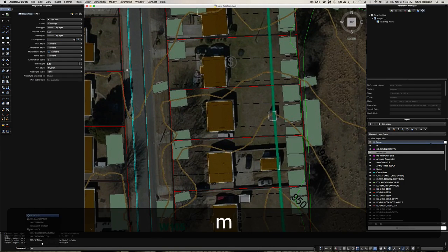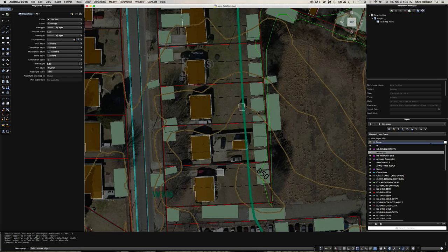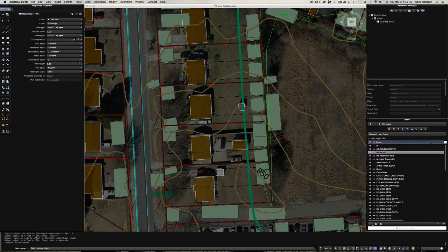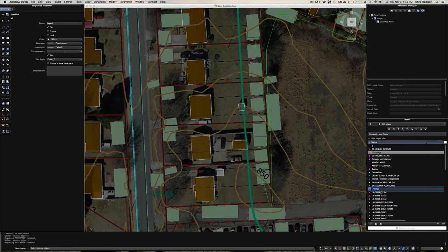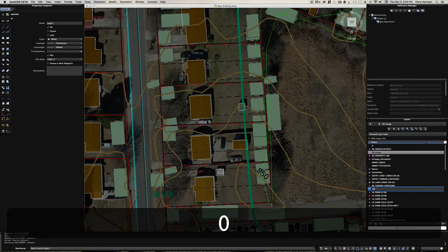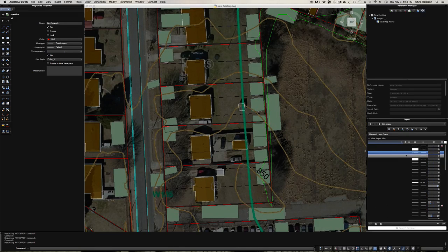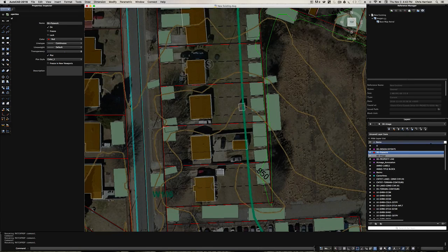And then the important thing is to change that layer, and either put it into a flat, I'd probably create a flat work layer. So let me go ahead and do that too, new layer. And I'll call this 0, 0, flat work. And I'll make that one red. And I'll just scoot over here. Okay, it's all good. So now what I want to do then is I'm going to double click on that to make myself current.